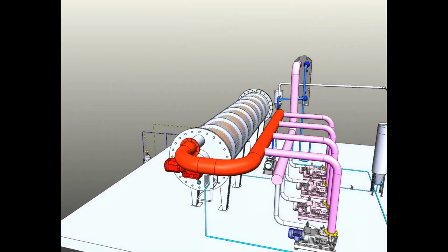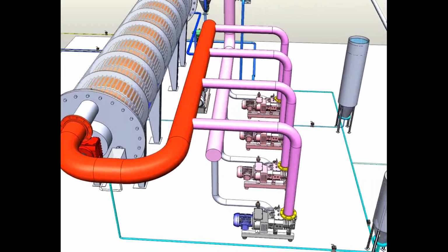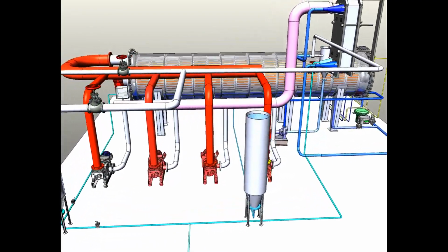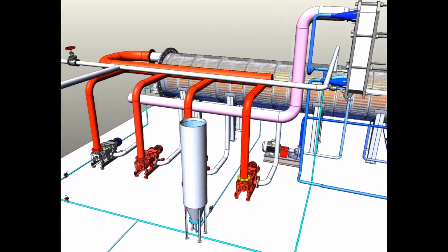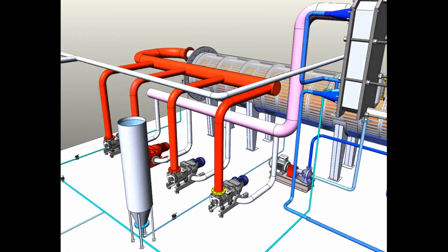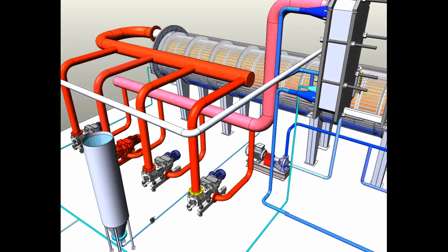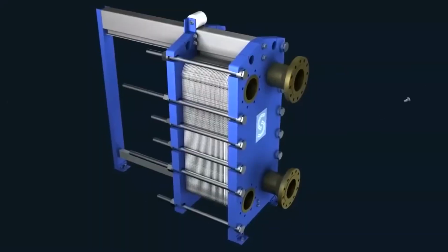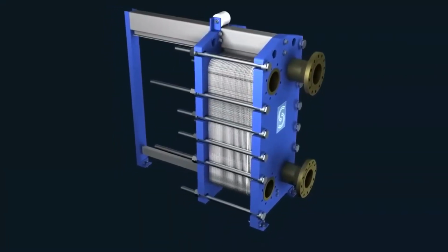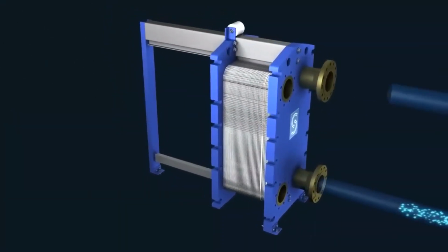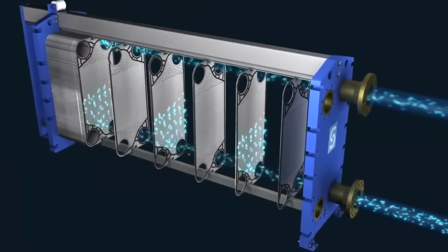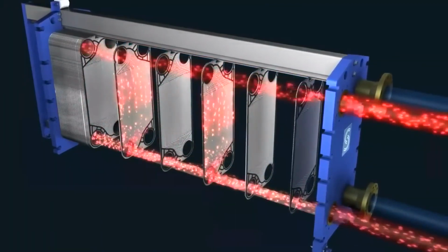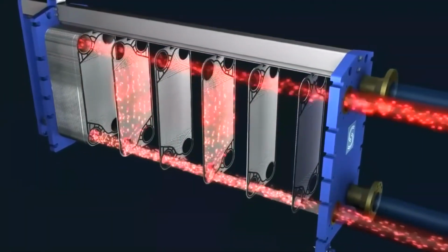The creation of the necessary conditions for isotope separation under vacuum is ensured by the use of 4-vane Elmo-Rietschle vacuum pumps of the RVWB series, which provide a volumetric steam pumping of 8,800 cubic meters per hour or 48 kilograms per hour. Compressed from 600 pascals to 3,500 pascals, the steam enters the plate heat exchanger, where it is cooled by a coolant with a temperature of 23 degrees Celsius and condenses into water with a temperature of 26 degrees Celsius, while heating the coolant to 26.5 degrees Celsius.